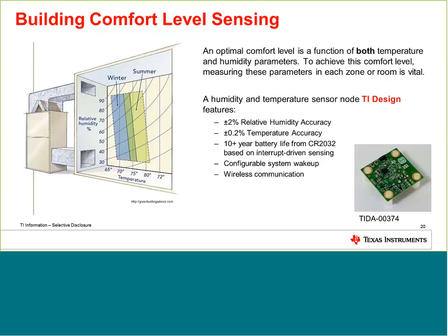So for that application, we specifically designed a TI design. You can see on the bottom right corner, TIDA-00374, and that has a humidity sensor with 2% accuracy, and there is also a temperature sensor with 2% accuracy, and it can operate from a single coin cell battery, CR2032, for 10 years, and it's interrupt driven, as I said.